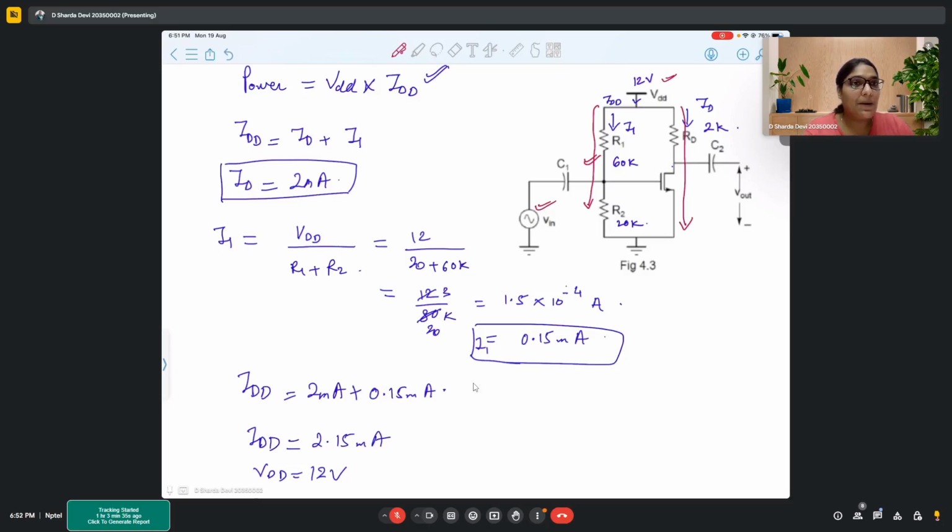So the limiting power will come from your power dissipation, but your input power will talk about gain, because with input power you will also find the output power, and from input power and output power you will find the power gain that you obtain from your amplifier. So that is different. This is power dissipation.